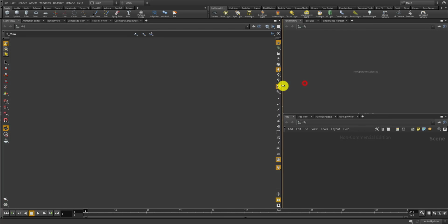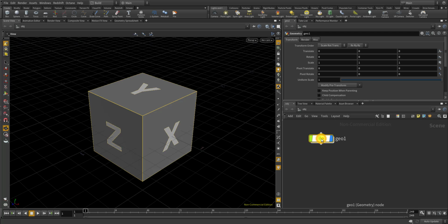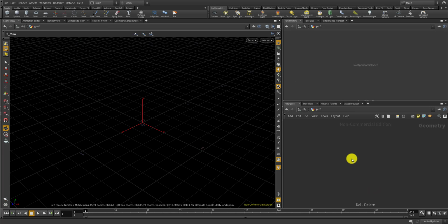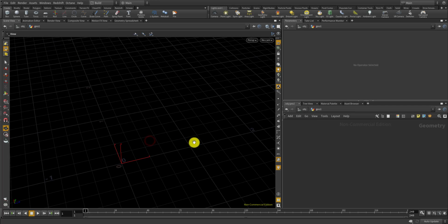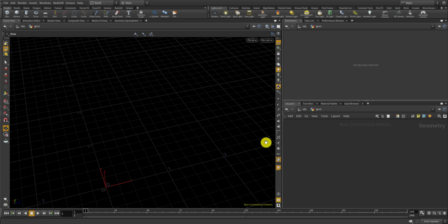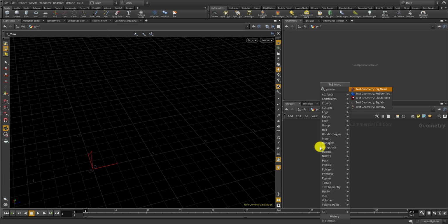So let's try that. Also the difference is that when you use 3D, the resolution or the pixels, or should I say voxels, that you're gonna use exponentially increases because of one extra dimension. So you cannot, well, you could, but you cannot really use high res like 500 by 500 by 500, since that's really huge for calculations. So I would suggest you go with the lower resolution first. Then if you like that pattern, then you can increase that later and maybe stay overnight for the renderings.